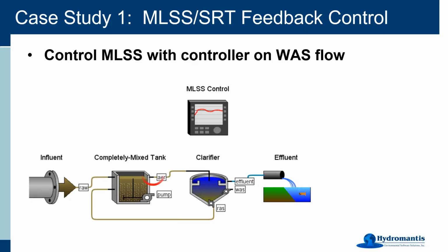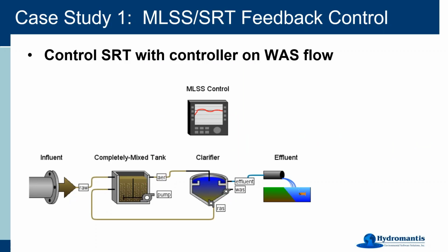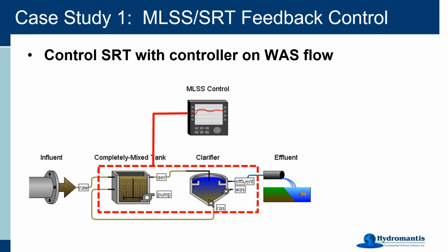Okay, moving on to same sort of thing, but we'll do an MLSS one. Sorry. Same thing, we'll do an SRT one. So very much the same concept. Instead of looking at the concentration of the mixed liquor, we can do it from the point of view of an SRT. So the SRT, the way I defined it, was actually solids here divided by the amount of mass flow of wastage here. So we kind of need this whole bit of information.